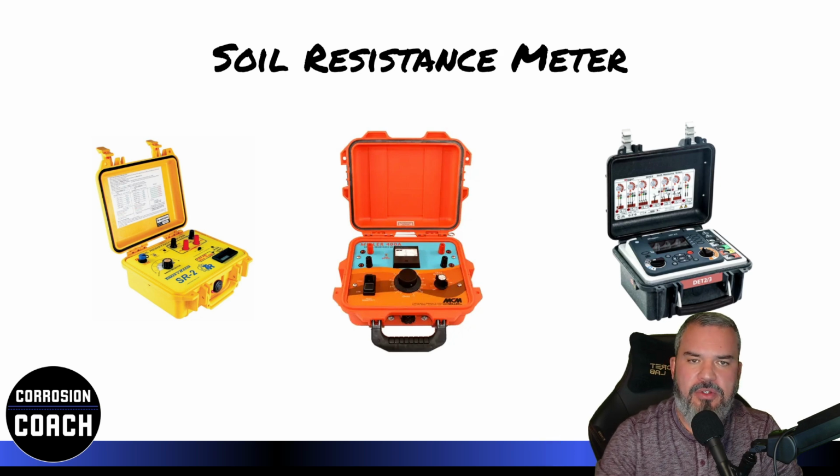The other one you see here that's orange in the middle, that's the MC Miller 400A, I believe is that model number. Again, been around for a long time. It's a soil resistance meter, does a really good job. And then the one on the right is probably a lesser known meter in the corrosion control world. It's made by Megger. You can look it up. This is a very good tool. This particular tool, of course, it's going to cost you a little bit more, but this particular tool is very good for measuring soil resistivities very, very deep. You may see folks in the grounding world use a meter like that. And there's some other name brands out there. These are just the three that I'm most familiar with.